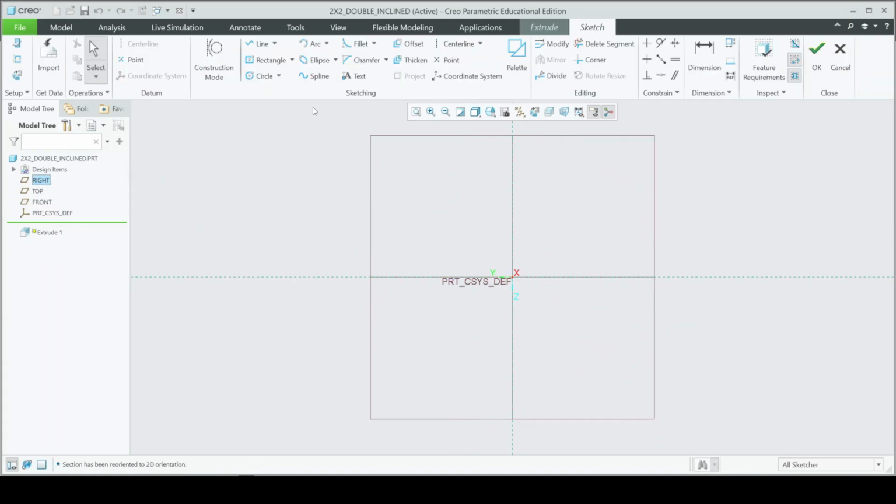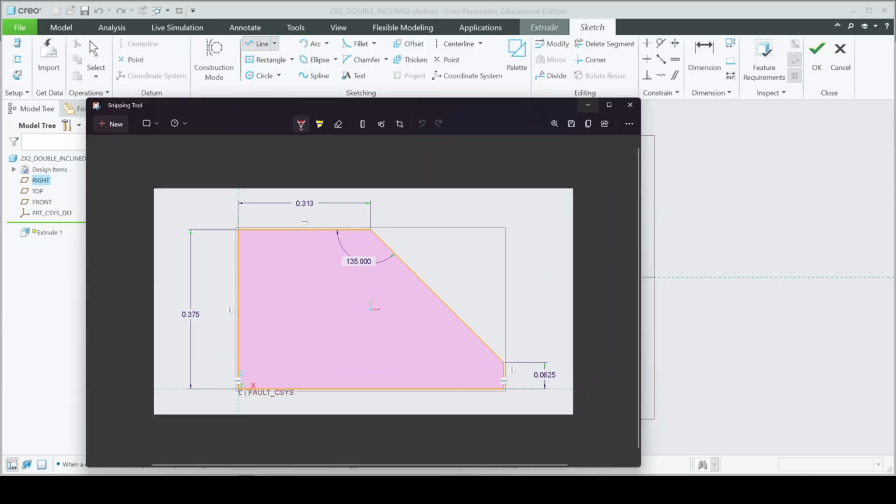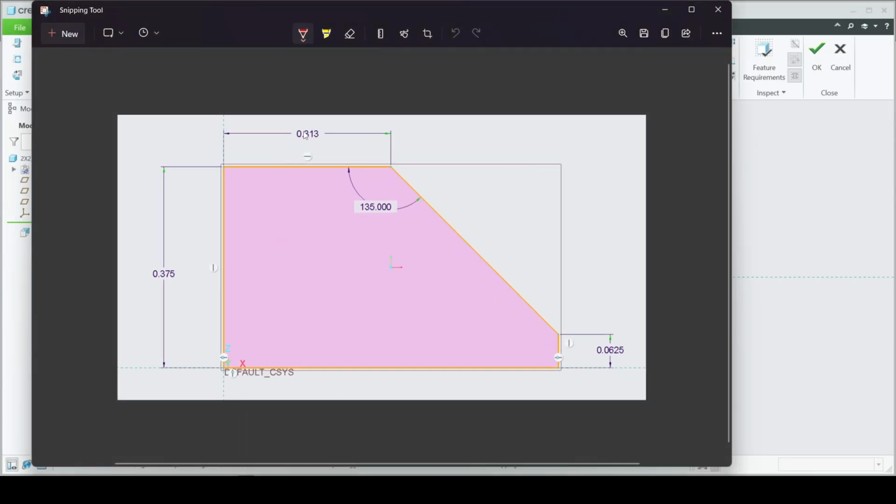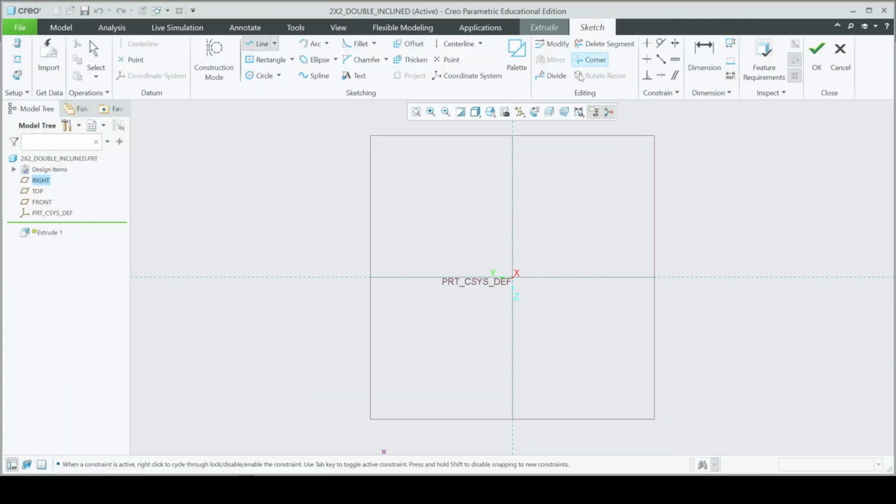And the problem, if you just try and use a line chain and draw out this shape right here, these numbers are going to be close to 100, unless you draw it very, very small. And then when you try to enter in some values, it may cause the shape to distort because some sides are much longer than other sides.